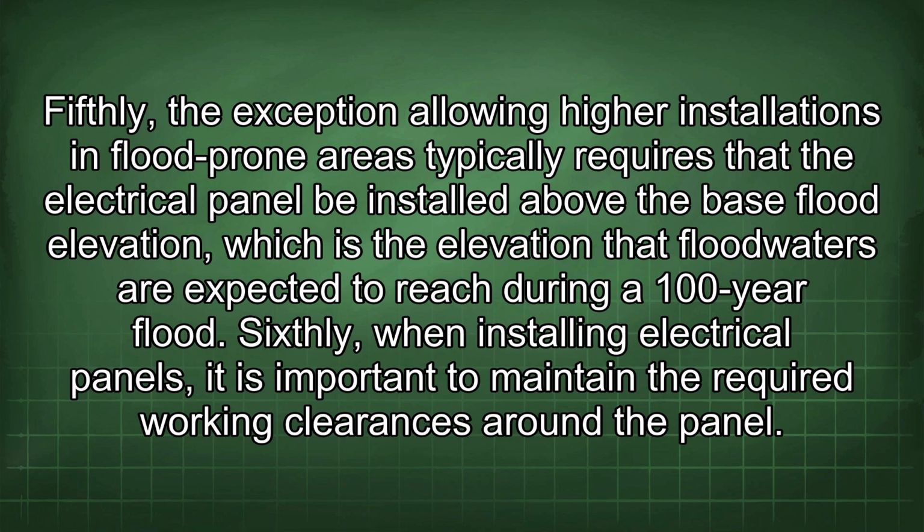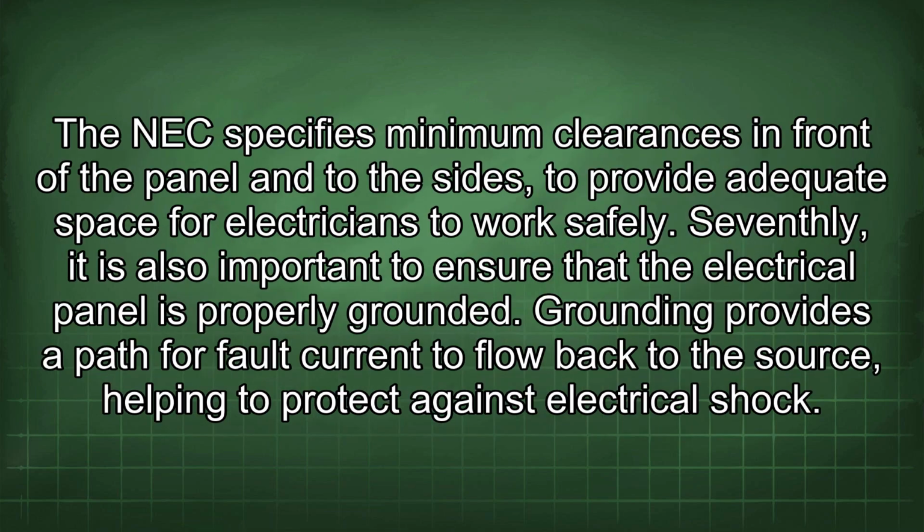Sixthly, when installing electrical panels, it is important to maintain the required working clearances around the panel. The NEC specifies minimum clearances in front of the panel and to the sides to provide adequate space for electricians to work safely. Seventhly, it is also important to ensure that the electrical panel is properly grounded. Grounding provides a path for fault current to flow back to the source, helping to protect against electrical shock.